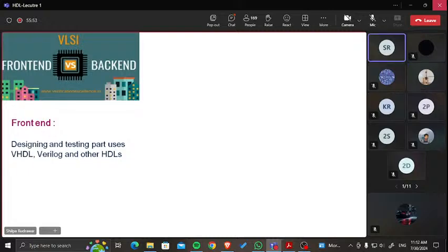And to check the correctness of your device means the hardware is there, the IC is there, and you are testing that. Do you say I am going to verify the IC? No, you are testing that IC. There is an IC tester, you put the IC in it and then you give VCC and ground, and it automatically tests. So that is testing, because you are checking the correctness of your device. Yes ma'am, got it. Verification is the correctness of your design, and testing is the correctness of your device. Yes, perfect.